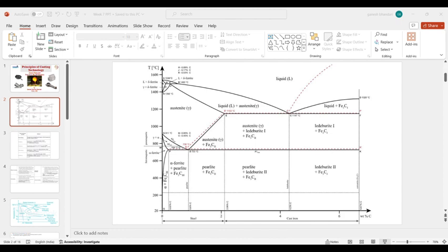During the cold working process, very high stresses are generated in that steel. Due to that high deformation, it gets very high hardness. So it gets some brittle properties inside that steel, and we cannot use that sheet directly for the deformation process, because for deforming that mild steel sheet, we need some ductility in our sample.